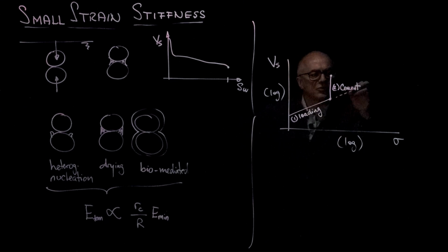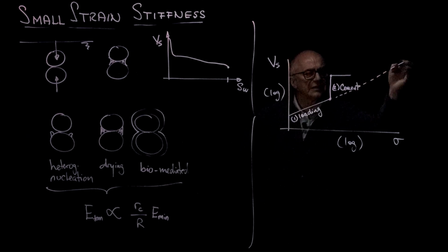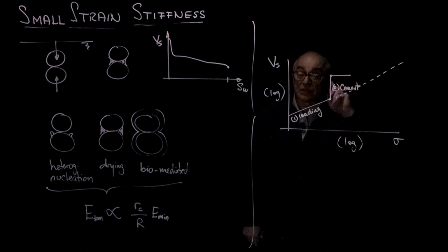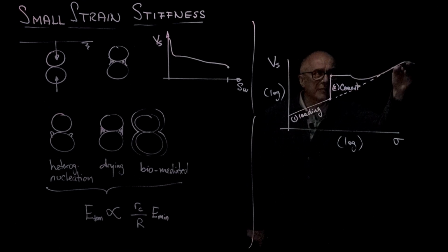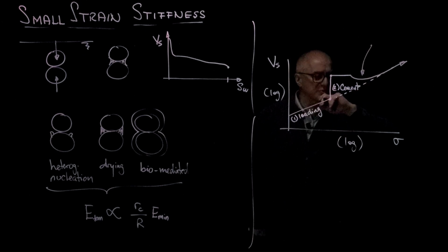So now what happens if during step 3 I decide to continue loading? Well, if I decide to continue loading, then the soil will experience almost no changes in shear wave velocity because it is cemented until it reaches the original trend where the particle deformation at contacts begins to catch up. Now, if the soil was loose, during this loading, the cementation may break and there is a structural collapse before it actually continues.